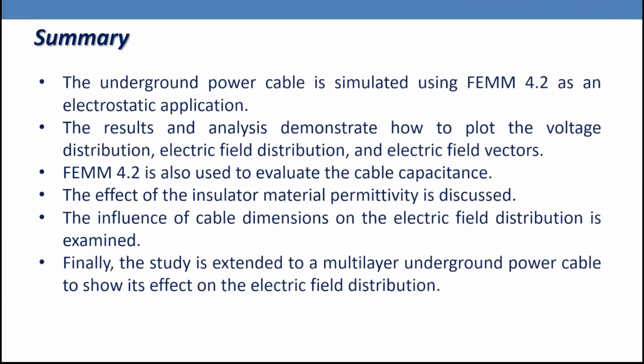In this video, we examined and discussed the underground power cable, which is simulated using FEMM 4.2 as an electrostatic application. The results and analysis demonstrate how to plot the voltage distribution, electric field distribution, and electric field vectors. FEMM 4.2 is also used to evaluate the cable capacitance. The effect of the insulator material permittivity is discussed. The influence of cable dimensions on the electric field distribution is examined. Finally, the study is extended to a multi-layer underground power cable to show its effect on the electric field distribution.